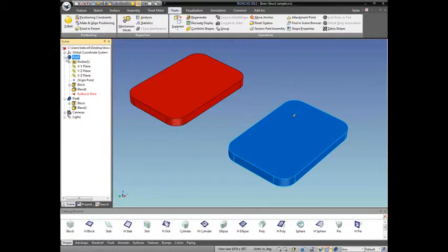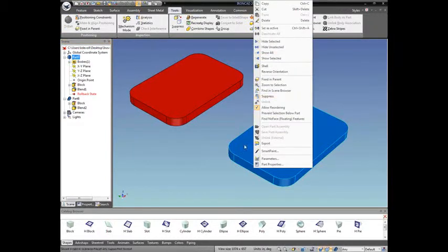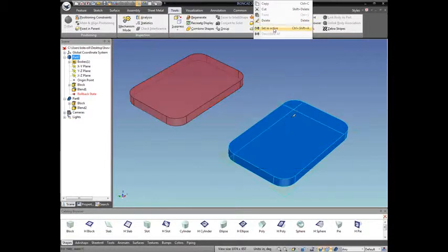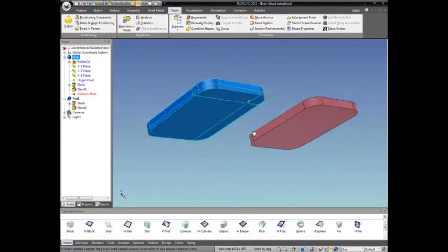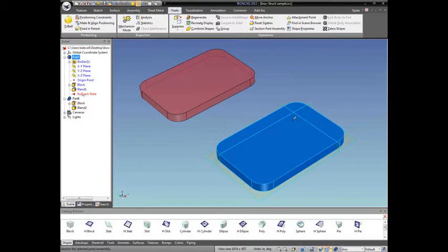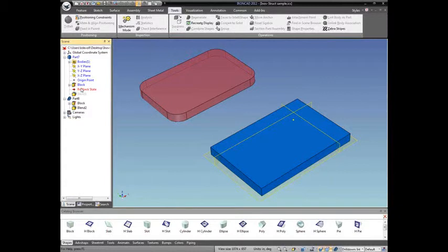You can see if we expand in the scene browser, this says the structured part, Part 7 here. It keeps track of bodies, like if you have disjointed bodies. It has planes, and you can see the planes if I make this part active. I can right-click on the part, hit Set Active, and you can see the planes around the origin. Then the features themselves, and this rollback state. This allows me to roll back to an earlier place in the model. That takes the blends out. We'll go over a little bit more of that later on.